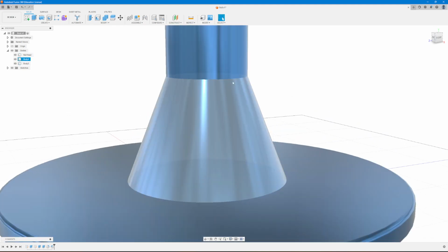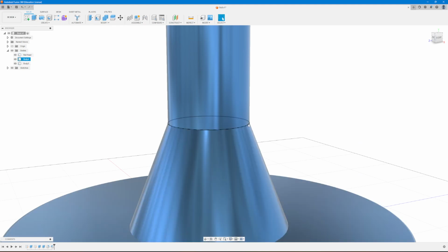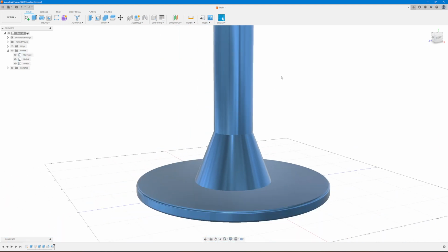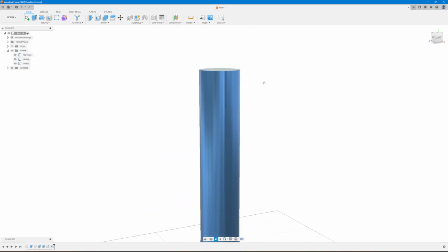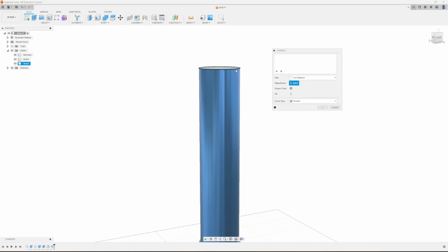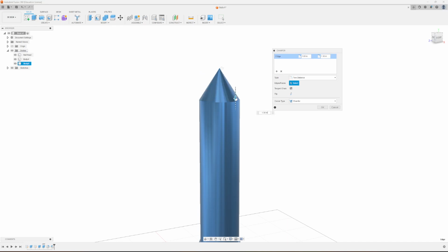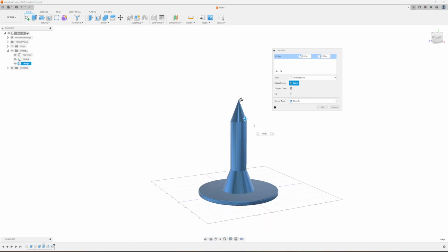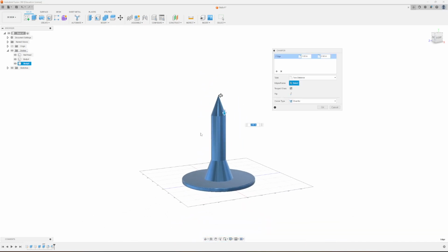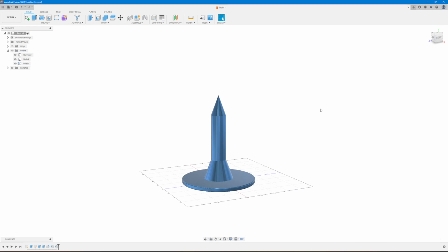We have the next bit, which is beveled, chamfered, I don't know, whatever. And now we have the top that we need to deal with. We could just round this off to a point by using a chamfer. Let me show you. Again, we want to do 2 distances. I want 1 distance that goes to a point, and I want 1 distance that makes this more of a nail. Actually, yeah, let's just do that. So this is more of a tack, really large, giant, uncomfortable looking tack that could impale a cow. But yeah, there we go. Simple as that.